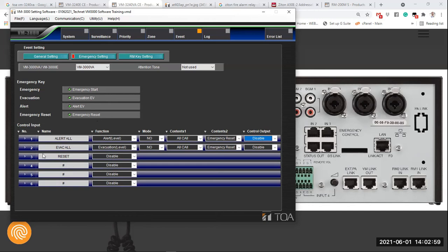All right. Then we are going to do the last one under emergency, our relay, which we are really not going to use, but can be used. So normally by resetting your fire panel, you reset over here. You can also have what you call a global reset, which is a relay on the fire panel that can do your reset. So what you do, you click on here and just choose emergency reset. You are done.